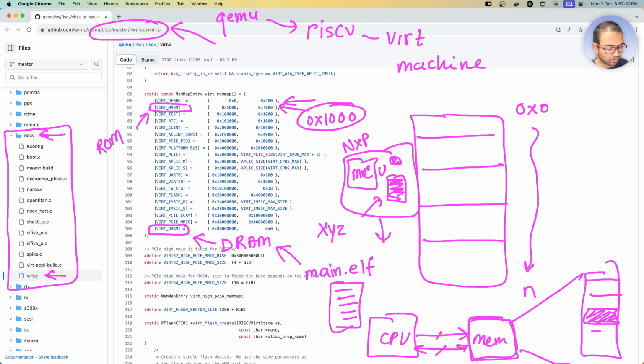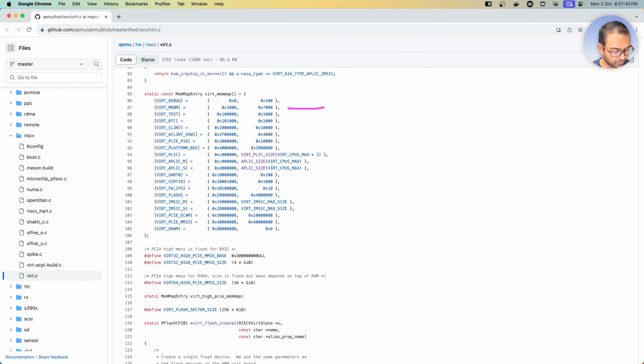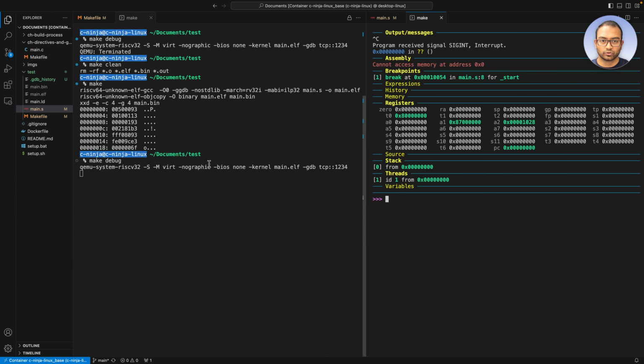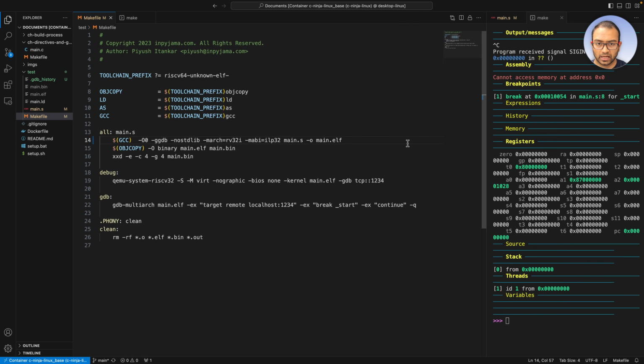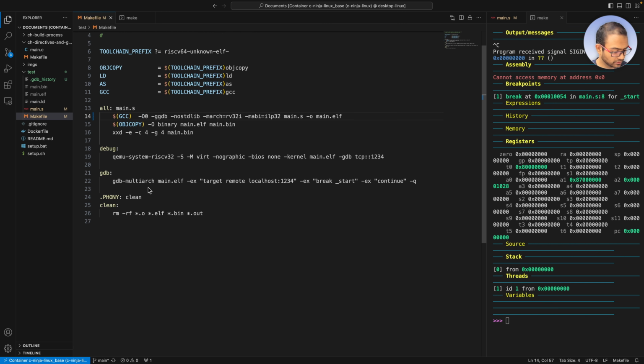So the idea then is there is a ROM, and ROM has some vendor specific code, which initializes something and jumps to the user executable code. So in this case, my claim is it will first start off here, execute a bunch of instructions, and then jump here, right? That's the idea, and let me just demonstrate that to you. To be able to demonstrate that, I'm going to delete a few more keywords from the Makefile, and those are the GDB-EX options, or values of those options.